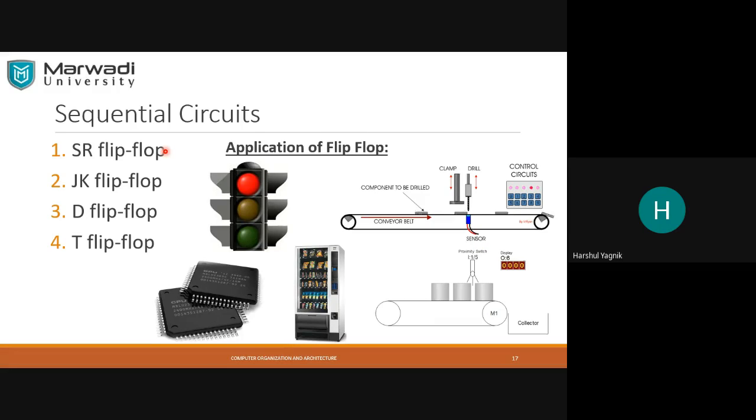Now for such applications, to design such systems which are based on memory, we need a memory, and memories are made from flip-flops. See, SR flip-flop, JK flip-flop, D flip-flop, T flip-flop. So a flip-flop is a basic memory element which has only two states, either 1 or 0. And that is why the name is flip-flop, that it can have only two values, either 1 or 0. Now what will be its value? That is dependent on what inputs we are giving to the flip-flop.